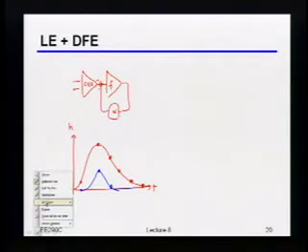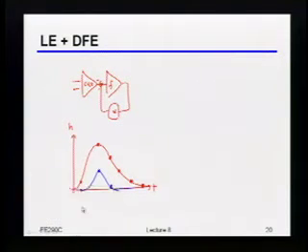So to draw it, let's say, approximately, and this time I'll do it maybe in black, what I would now get is maybe something that, just out of the linear equalizer, kind of looks like this. Okay, so I still want it to be 0 at these other points, right? But now I've allowed myself to just leave some ISI there on that very first post cursor, right?